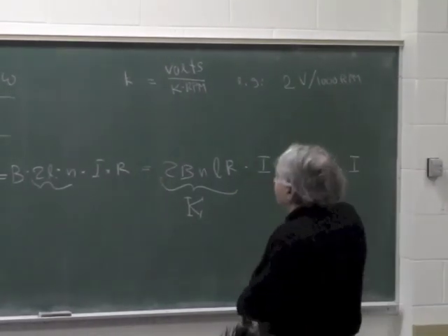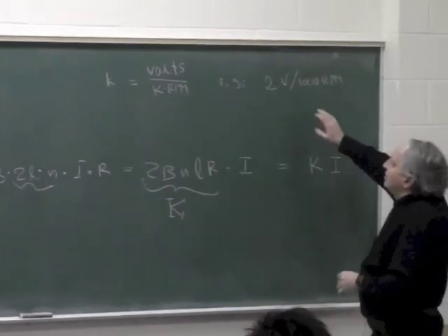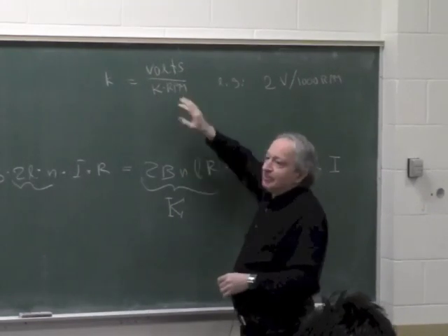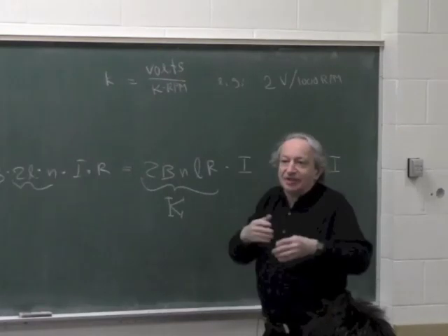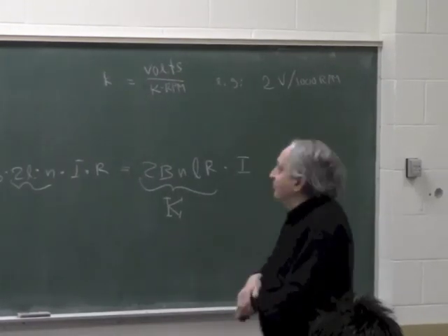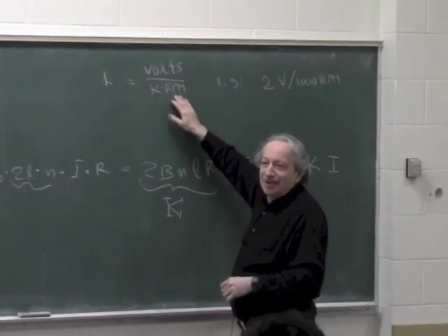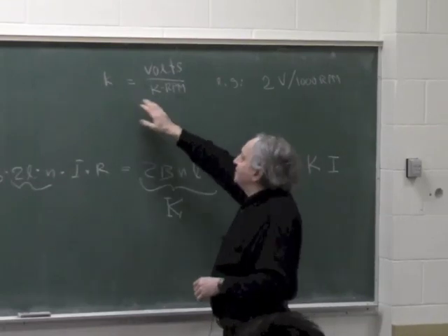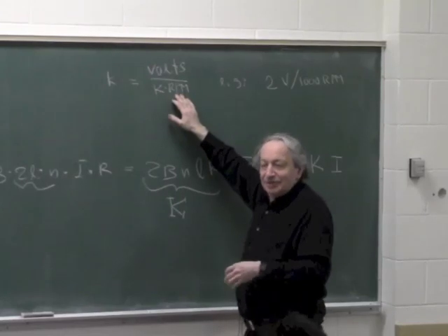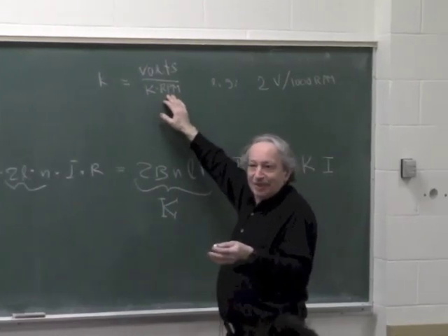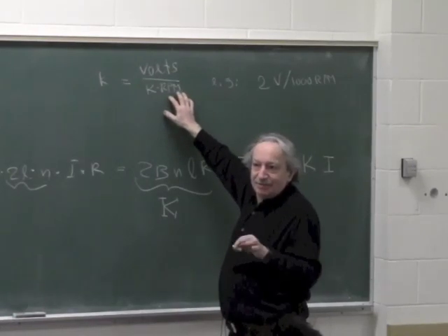So these two are the main parameters of the motor. So the same K, which is given as volts per kilo RPM, is also a Newton meter per amp, assuming they normalize the units, right? Because RPM is not an MKS unit, so you'd have to convert this to radians per second, right? Because for RPM you have to divide by 60, multiply by 2 pi, so this will become radians per second. Is everybody clear on that?